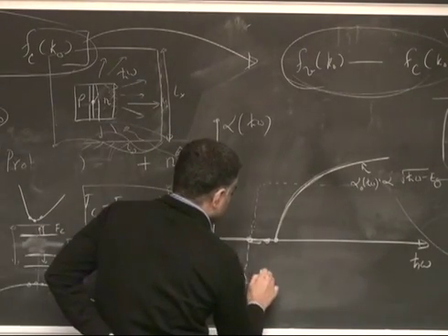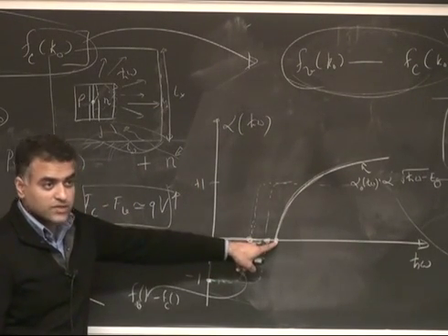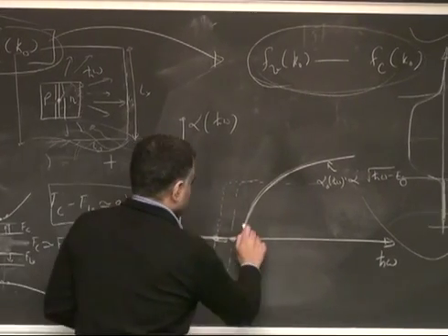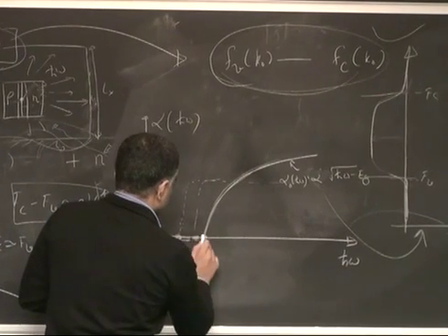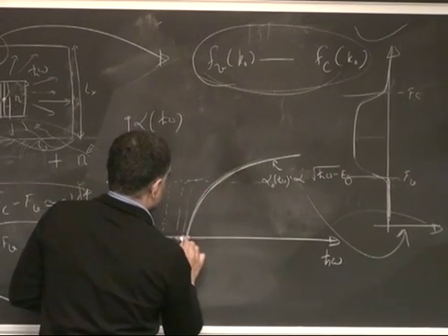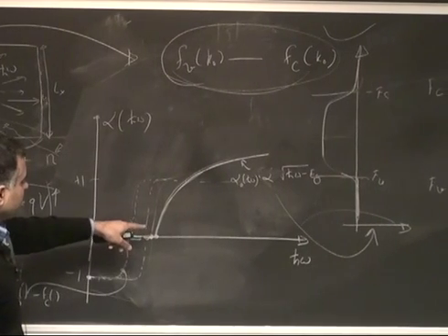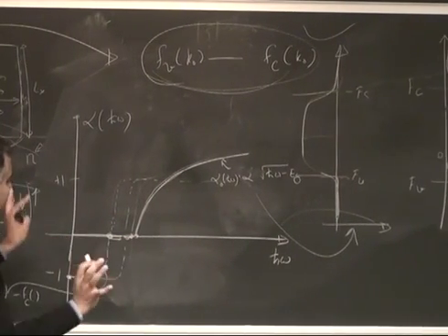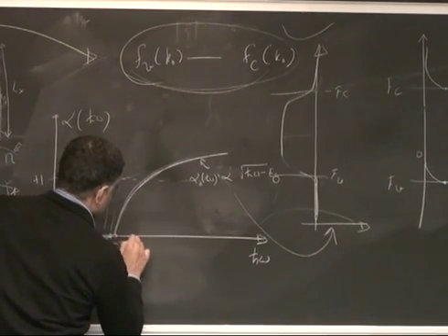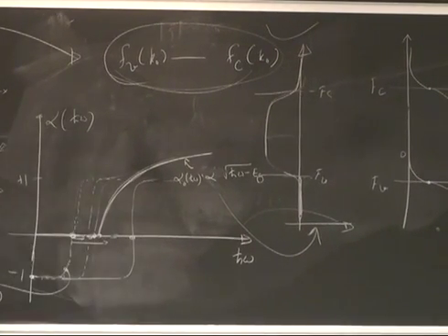And I think you can see very clearly that there is a very clear threshold. When this crossover point reaches the edge of the gap and goes above it, then something interesting is going to happen. Till then, you are here or very close, and then it goes over like that, and you get the highest. Essentially this is the spontaneous emission process, because NP has become larger than ni squared, but the moment you cross this, and let's say your injection is such that your function looks like that.